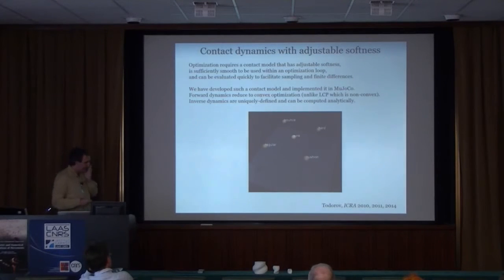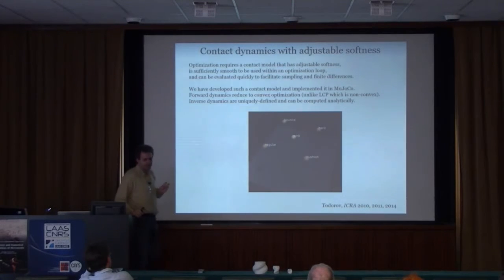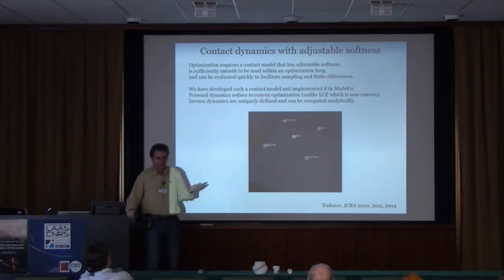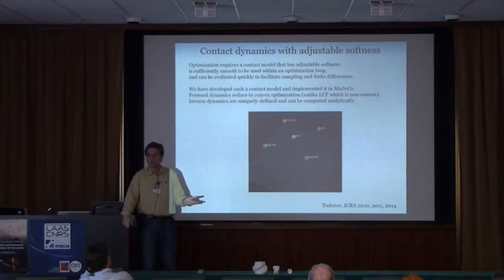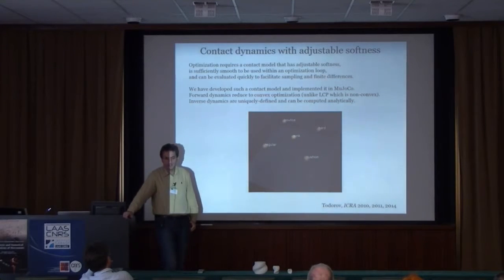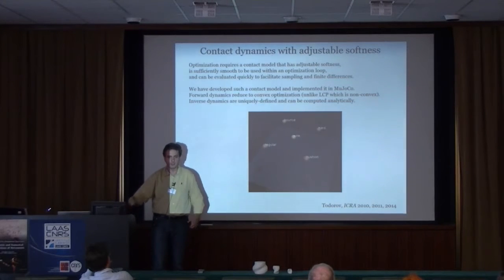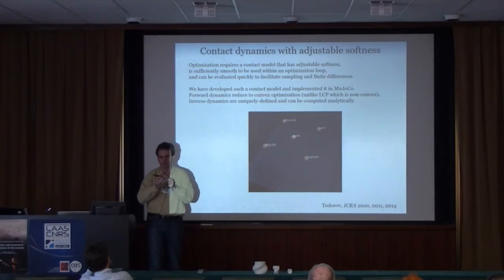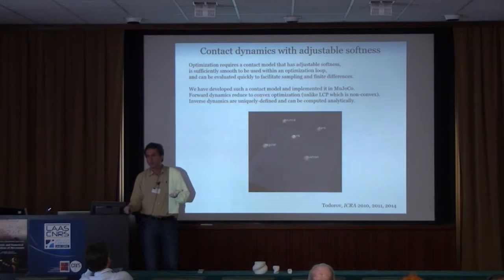So the key behind it is the treatment of contact dynamics. Now you might have thought that physicists have solved all these things, so why do I even bother talking to you about it? And the answer is that no, actually they're not solved. The reason they're not solved is because what we're trying to simulate is rigid body dynamics, and contacts are inherently non-rigid phenomena. It might sound like they're rigid, but really it's all about the deformation of the little materials here. The only right way to do this is to solve a PDE, but nobody has the time to do that.